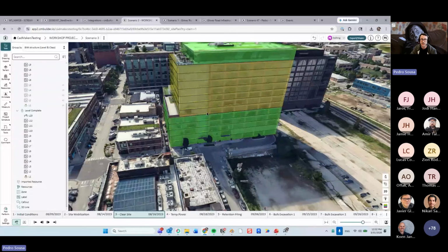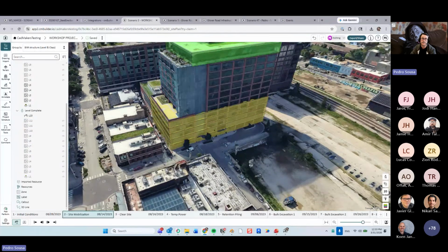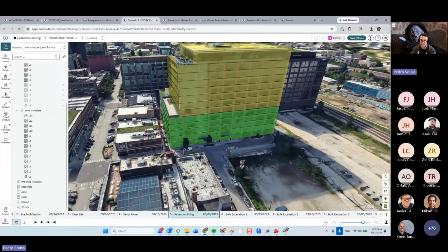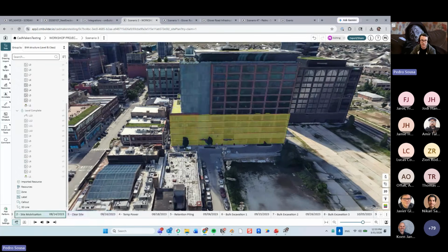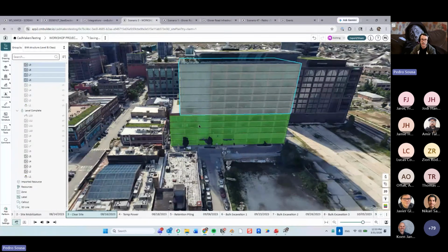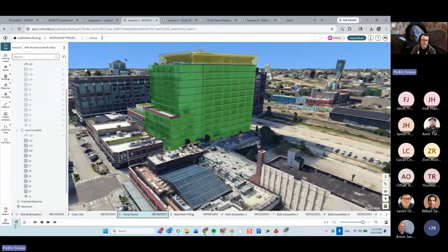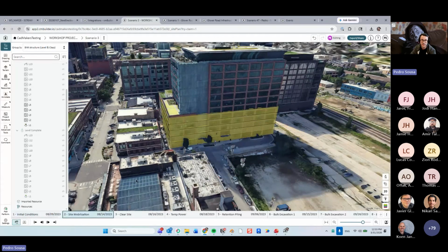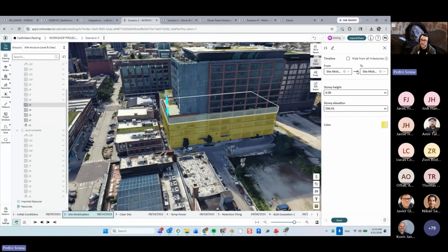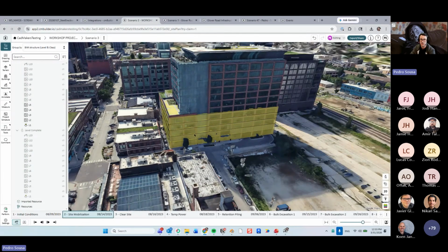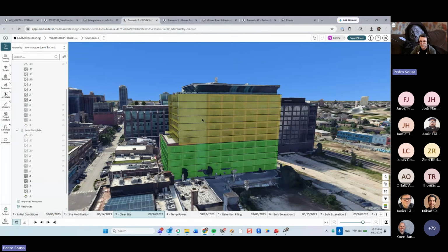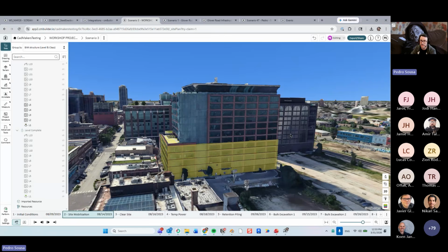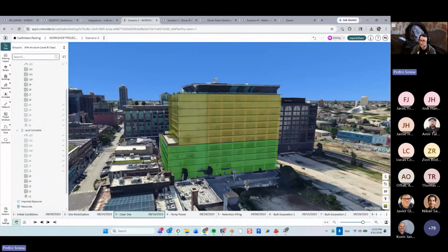So that way you can play around with that and put these different color coding elements at different stages, right? So now if I go to the last one over here, I'm doing it quickly with my keyboard shortcuts, Control B and Control E, so you can assign things to the milestones quickly. Okay, so let's take these guys and hide them in here, and then these guys and hide them in here. So basically, on milestone number 2, I decided to start and end these levels at the same milestone because they will show just the yellow colors. And then when I go to the next one, the green colors will show up, and the yellow ones will show up consecutively. So you have a way of color coding this work being done in different stages.